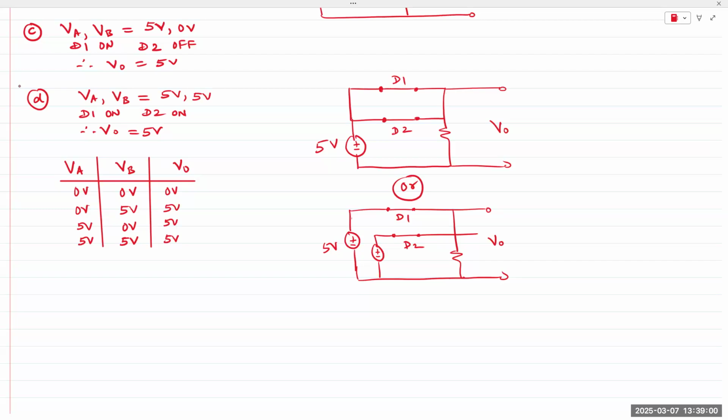Why specifically 3.3? That's the lowest voltage they found that they can create digital logic circuits with appropriate noise margins, because we have to have certain noise margins. So if it's 3.3 volts, you can say anything between 3 and 3.3 volts is logic high, and anything between 0 and 0.3 volts is logic 0.